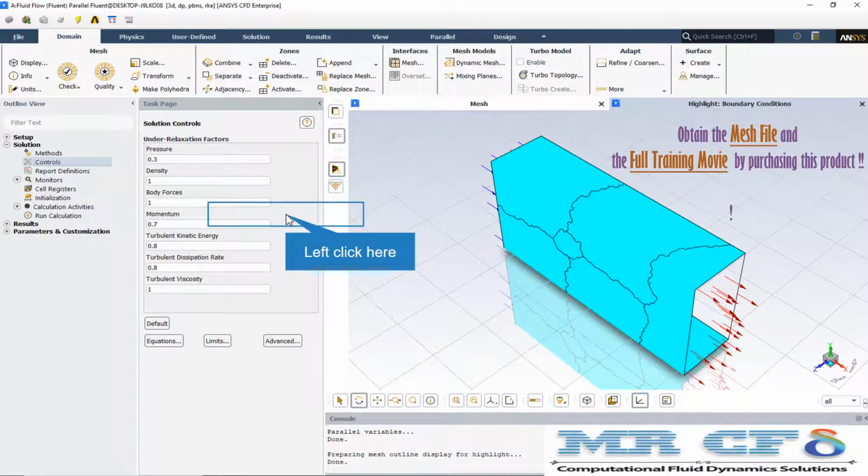Occasionally, you may make changes in the under-relaxation factors and resume your calculation, only to find that the residuals begin to increase. This often results from increasing the under-relaxation factors too much. A cautious approach is to save a data file before making any change to the under-relaxation factors, and to give the solution algorithm a few iterations to adjust to the new parameters.